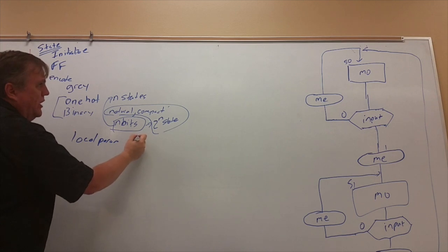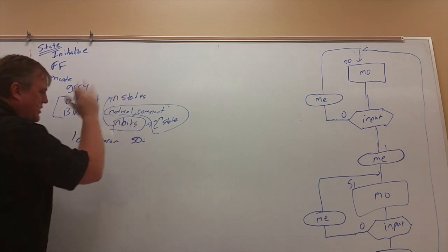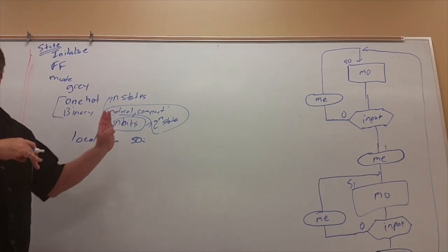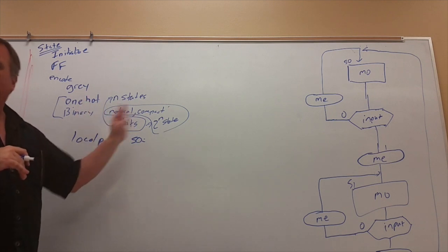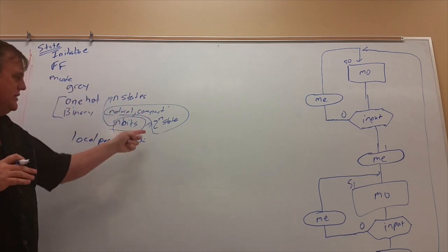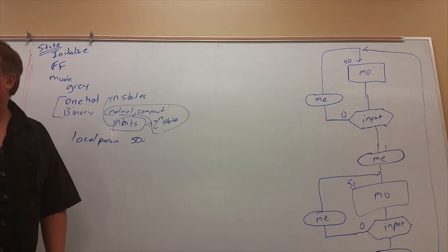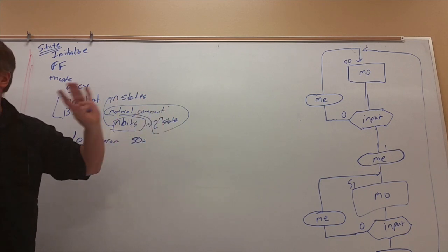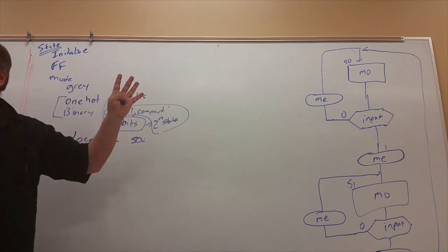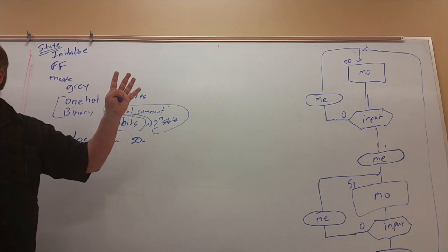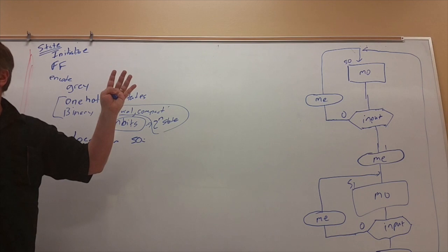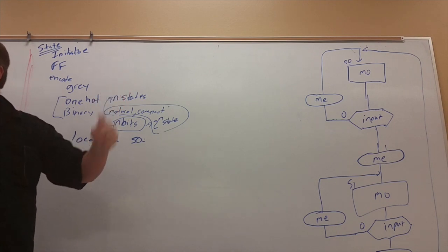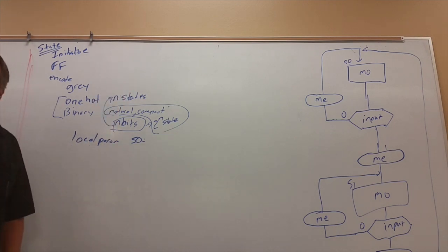and then we would just say whatever, S0, and we would set it to be equal to whatever. And we could specify that it was a reg of whatever size. But we could basically set these S0 and give it a number. And that would allow me to specify the encodings. If I don't specify the encodings, what happens? Xilinx gets to pick. Anybody know what Xilinx picks by default?